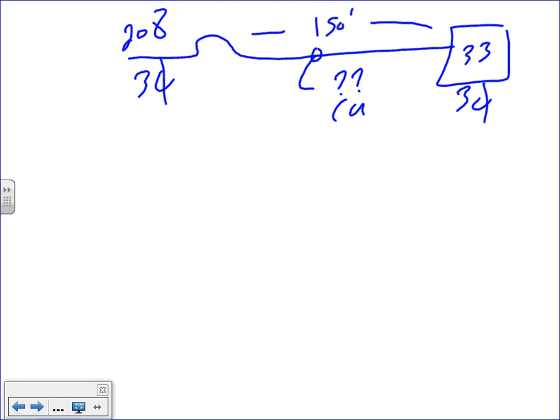Can you repeat your statement? Yes. Good point. Can I feed a single-phase load, 33 amps, from a three-phase 208 system? Can I? Why not? You're just taking two phases. So this doesn't have to be three-phase. In this case, we assumed it was three-phase because of our example.